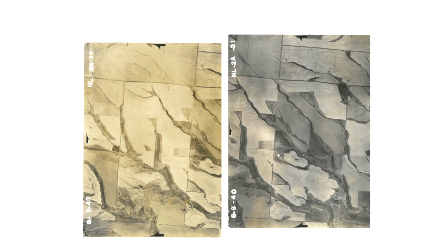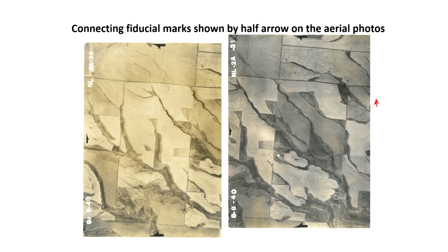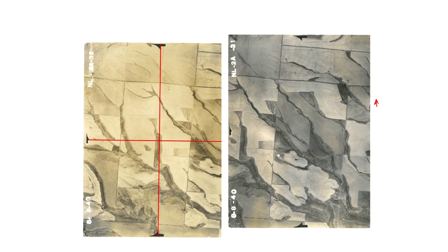So, determination of the line of flight, if you take the same photographs that have been taken here. So, you have a slight change, okay, because it has been marked here. So, this photograph is slightly up here as compared to this one, but you have fiducial marks. So, you can connect the fiducial marks and then obtain your principal point.